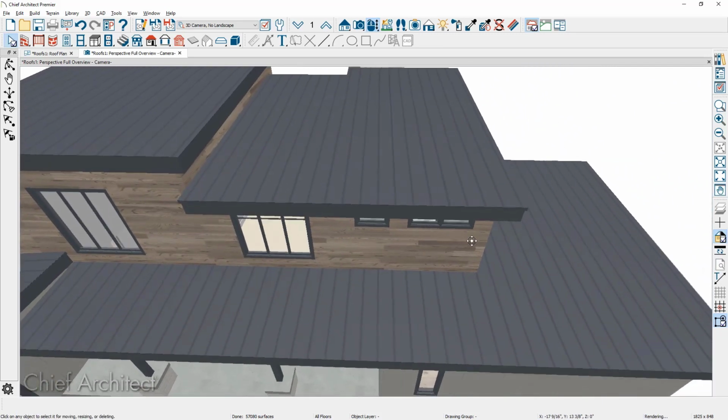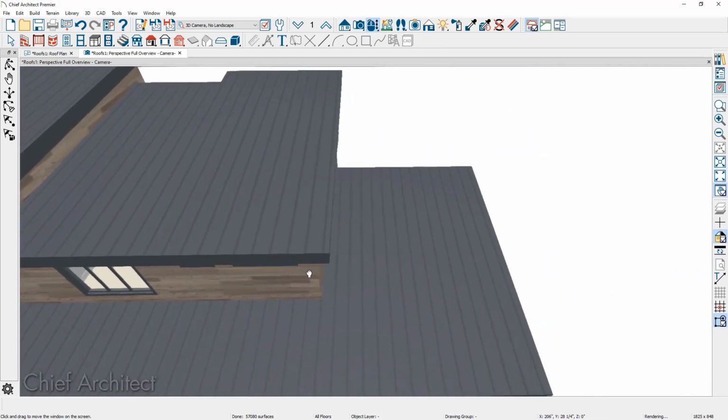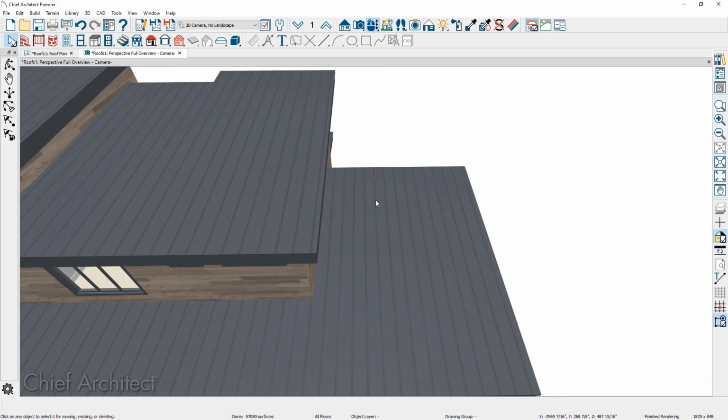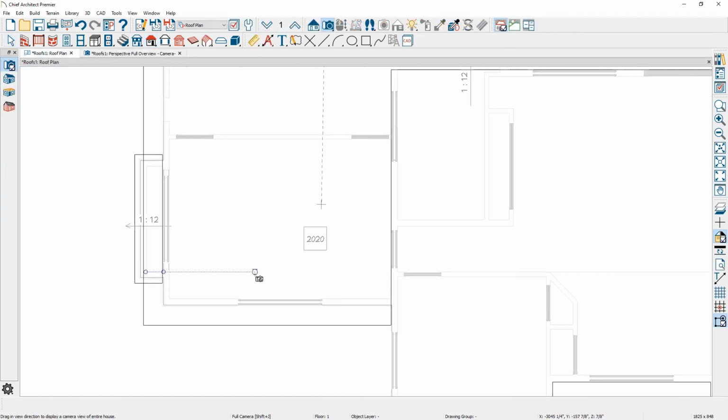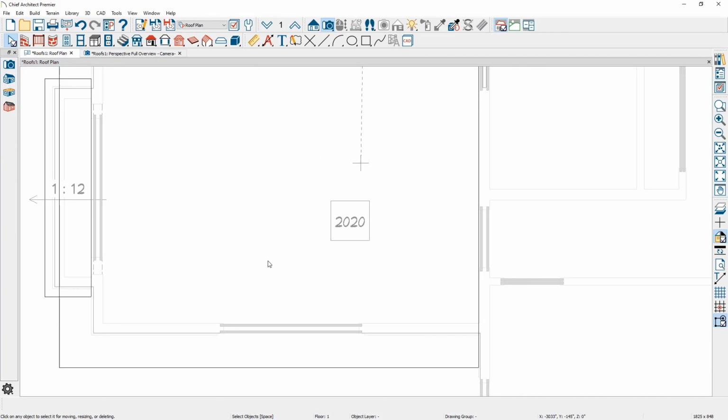Let's begin by placing a couple of skylights, and let's do that over the primary bedroom area. Underneath the roof panel, let's come in and grab our skylight tool, and I'm just going to click and place the skylight. Now when you are placing the skylights and you care about the exact placement of it, you might turn on your roof framing in a floor plan view so you can position those exactly. Let me go over into the floor plan view. Let's go ahead and zoom in where we place the initial skylight.